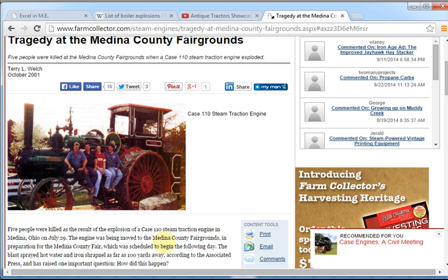They weren't trying to show it off, and the safety valves were not at fault. What was at fault? It was old. It had some rust and some deposits and some erosion of the material, and it wasn't as thick as it was when it was brand new. They traced it all down. They have a full report. You can look at it too. They just underestimated how much loss of integrity the metal could handle. So all the time I say it's metallurgical considerations that limit our pressure and temperature. It's definitely true. Okay?